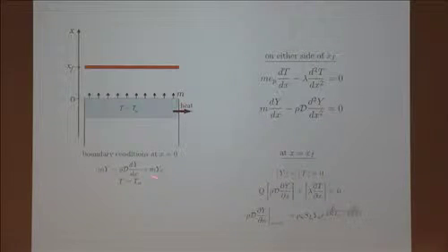So the flux of fuel in is only a convective flux, m times Yu, and the flux out also has a diffusion counterpart, okay? So the net flux is convective and diffusive. And you see the diffusive is, of course, with the diffusivity of the fuel, which is just this script D. So those are the boundary conditions.